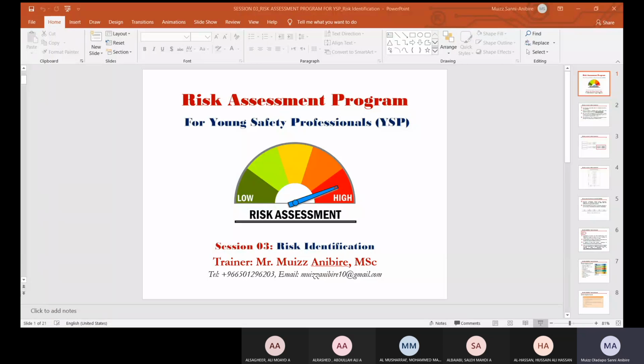Now let's look at this as well. If you look at this diagram, we have firstly establishing the purpose and scope, as we discussed previously. So you establish the purpose and scope of your risk assessment or hazard analysis. Next, you identify the hazards. It could also be failure modes, if it has to do with equipment or some systems, where you could identify possible failures. So you identify failure modes. Next, you identify current controls.